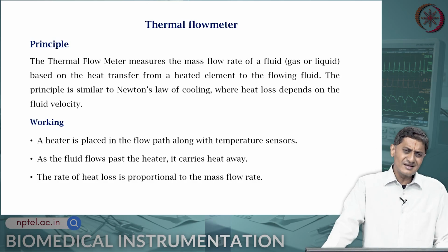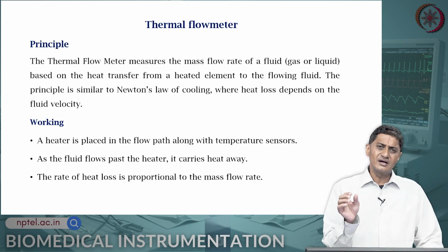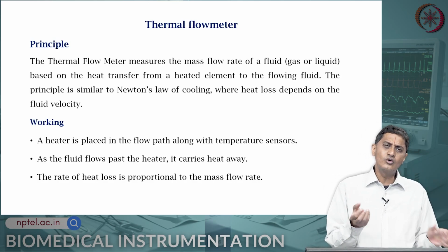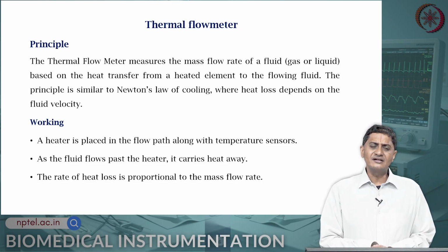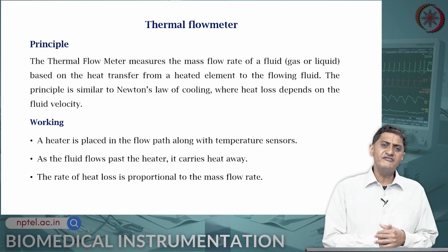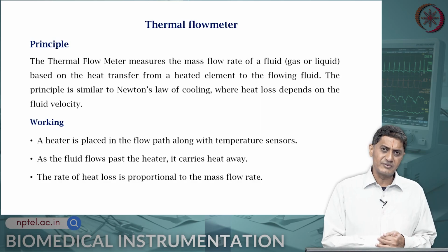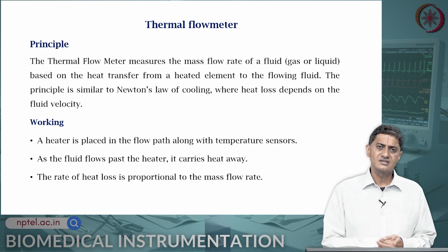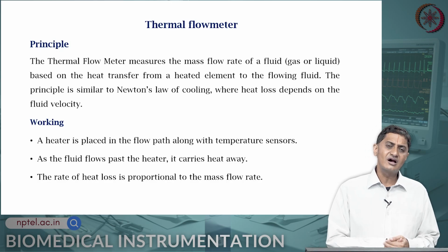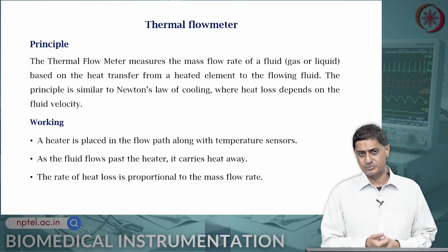So, that means I heat up and see how cool the fluid becomes at a known distance away from the heat source, for example, or how hot the fluid becomes at a known distance away from the heat source. I can estimate how much of the fluid has flown.